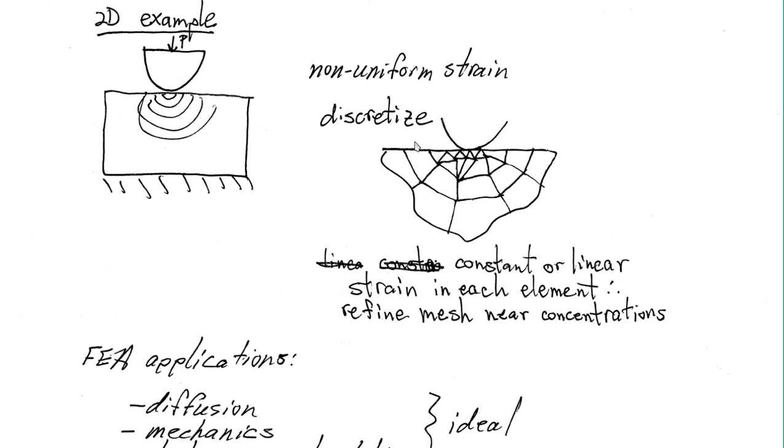Well, when we solve this with a finite element problem, remember I said we have to interpolate between points. So you get solutions at these discrete points. If you have very large changes in your stress as you move away from this point, you need to resolve those differences here.